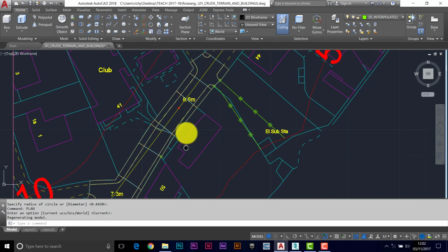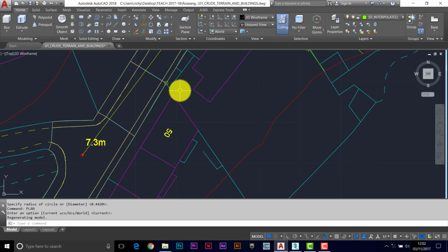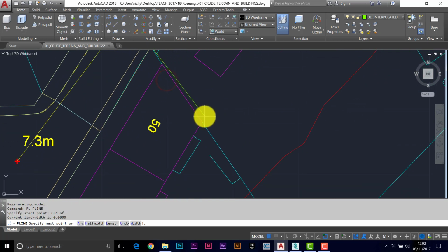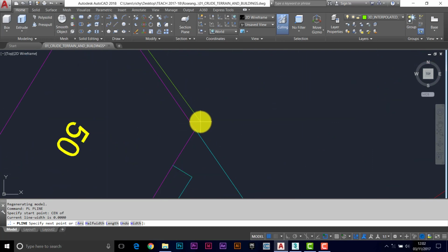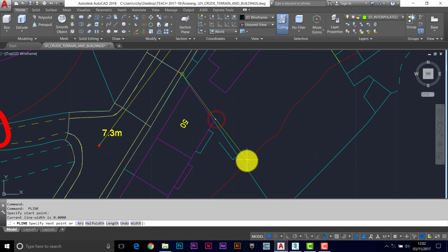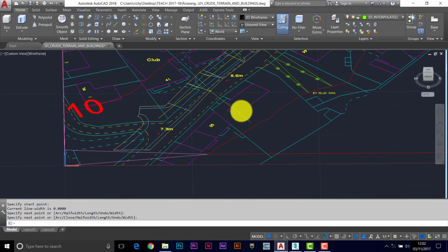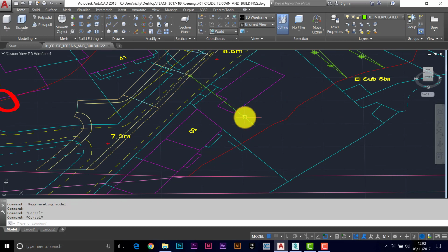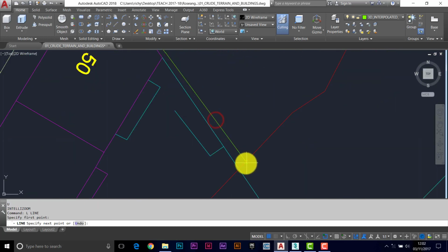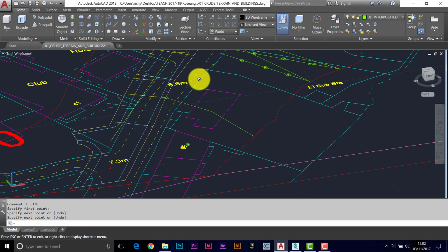Okay, and get in a bit closer. And we've got buildings here. So let's do a level line, so a polyline to say about here. Okay, and then it'll be a normal line from there down to the contour. Oops, must have done a polyline there, excuse me. So a normal line from there to the contour. Let's have a look at that, that's better, sloping now.